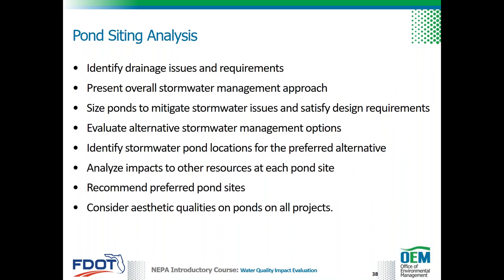The conceptual drainage and pond siting analysis look at existing and proposed drainage conditions to identify issues and requirements for an overall stormwater management approach. Ponds are sized to mitigate stormwater runoff and to satisfy design requirements, taking into account alternative stormwater management options. The project alternative must incorporate recommendations from the environmental look-around process and include analysis of pond locations. Resource impacts are evaluated and preferred pond site locations are identified. Aesthetic qualities of ponds are considered on all projects.